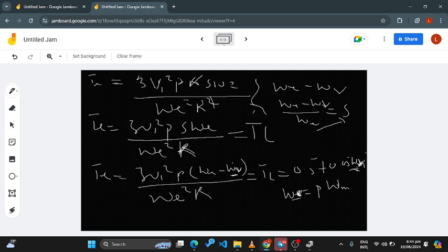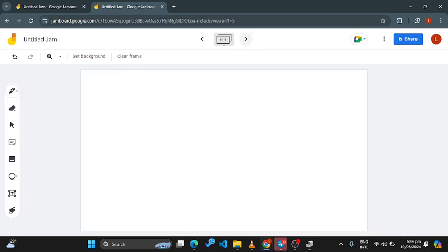So now for the load torque equation, we are replacing the omega r by omega m. And we know that omega r is equal to P omega m. So now in the electromagnetic torque equation, we are going to replace omega r over here, which is the electrical speed, by its equivalent mechanical one, which is P omega m. Is that okay? So now let's do that and solve.